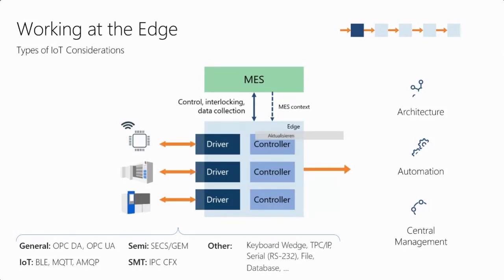So the factory's MES system is the place where we do all the active real-time tracking and monitoring. Okay. So these are all the general protocols which we use. We would be studying a lot of IoT protocols like MQTT, AMQP, but mostly in industries, especially in Germany, in Industry 4.0, we use this communication protocol called OPC-UA. It is a very general, open protocol for communications. The biggest advantage of this OPC-UA standard protocol is that it's been backed by IEEE. This protocol will act as a data exchange mechanism across multiple vendors. So even if we have a different vendor like Siemens, or even if you buy something from Rexroth, both of them can communicate with each other using OPC-UA.